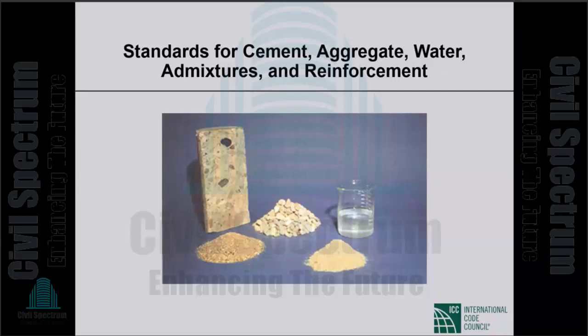The concept of pre-stressing is we put the concrete under compression before any loads come on our structural member. And the idea is then until this pre-compression is overcome by tension, the member is not going to crack or fail. There are two different ways of applying this pre-compression on the concrete. Both involve pre-stressing steel, and that's also something that we will talk about just a little bit.